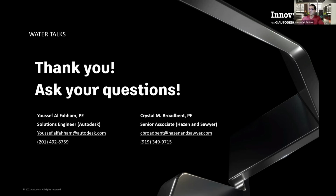And then there was a question on how do you address a system which does not have much information on its air valves? Well, most water distribution systems don't have a lot of information on their air valves. Yeah. A lot of distribution systems don't want to have air valves or maintain them. Usually, because the goal for water systems for me is 0 PSI, the air valves should never open if you're keeping pressures above 0. So I don't push to put them in there.